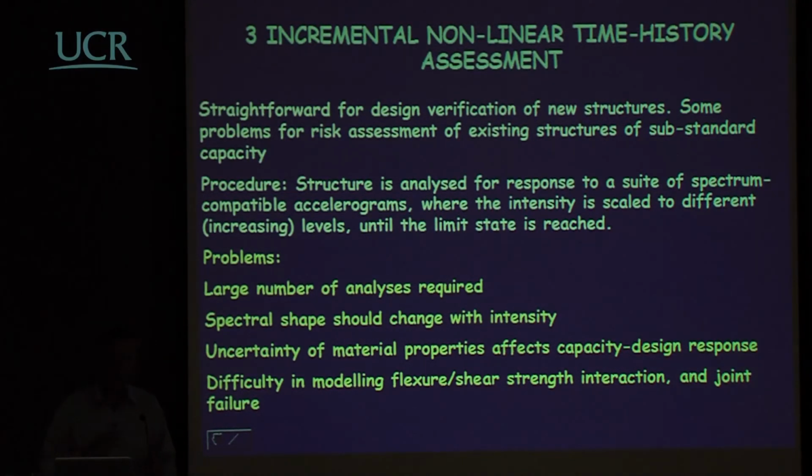We should be using in each level of analysis a different spectral set which represents the probable risk associated with that level. For example, if you're talking about a 50-year return period, this will definitely be dominated by small earthquakes close by. If you're talking about a 1,000-year return period, it's probably dominated by a large earthquake at some distance. And the shapes of these will be completely different, so you can't get anything valid by just scaling the spectral set. Again, there are the problems of uncertainty of material properties affecting capacity design approach.